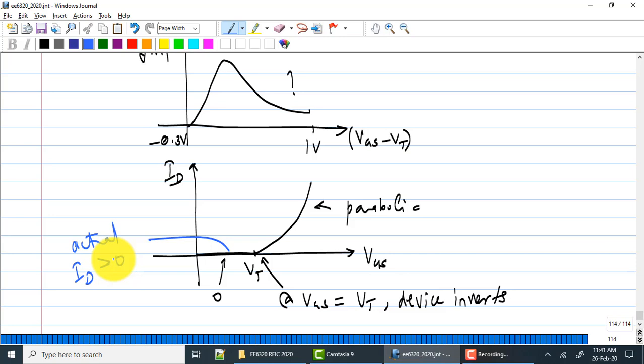After the region completely depletes, the device can conduct very small currents. It goes through regions. The device goes through regions of what are called weak inversion and moderate inversion before it hits the strong inversion region, where it can conduct much higher currents. In the device modeling course, they would have seen this.